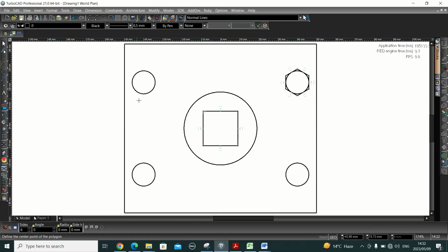Now we need to draw this one. Same procedure. Define now the x coordinate is negative 40. Remember from our last circle. Y is 24. Press enter. Now the segment mode is still there. Don't worry about it. You need to change only the angle is 60. The radius is 6. Press enter. There is your hexagon. Now we need to draw this one here. The coordinates here, they are all negative, x and y.